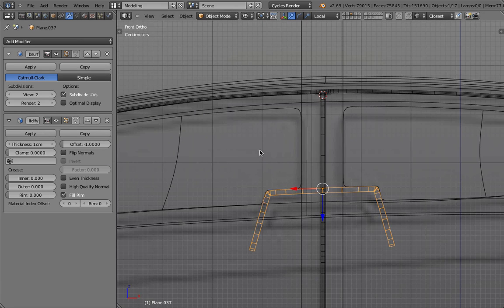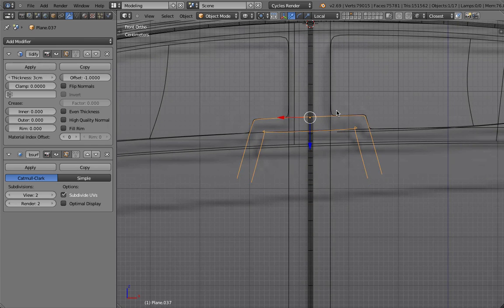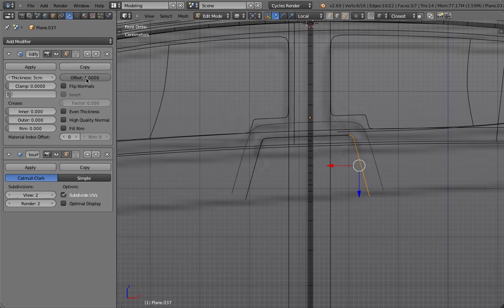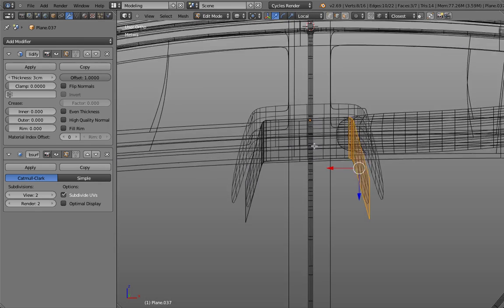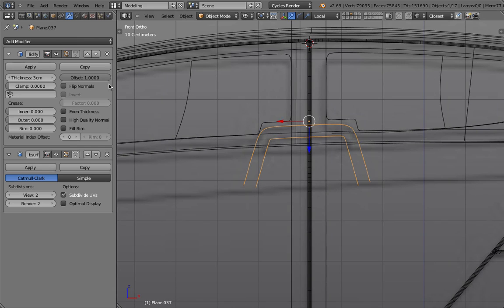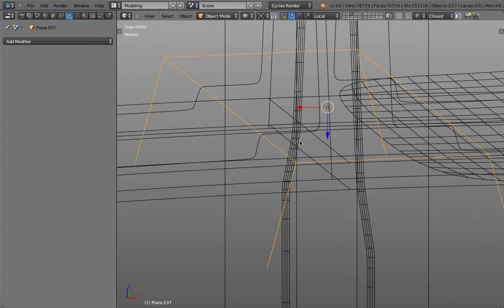Then we can actually make use of the solidify modifier again, a second time. Try to scale it down, and there we have this intersection issue. So this means solidify modifier first, and rats, doesn't work. So what do we do? Well, this radius is just way too small, so there's no other way. Instead of shrinking it inside, we just let it grow to the outside. Let's see if this works. Yeah, this doesn't work as great either. So that was a great thought. Unfortunately, it doesn't work. So I undo everything till, for example, I have this edge rounding,